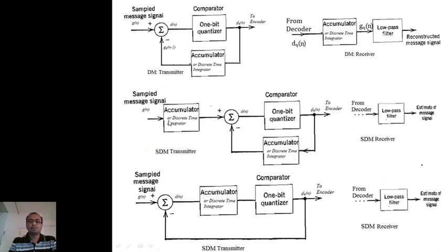Yes. If I move this accumulator inside, take this dqn directly here along with gn, first generate the difference signal gn minus dqn, and then feed it to the accumulator. It is the accumulator transfer function multiplied by this difference signal dn, which is the same as accumulator into gn minus accumulator into this. So if I take the accumulator common, I need only this difference signal and then multiply it by the accumulator. In this way, I have replaced the two accumulators by only one accumulator. So I have not only reduced the hardware, but I have also reduced that problem.